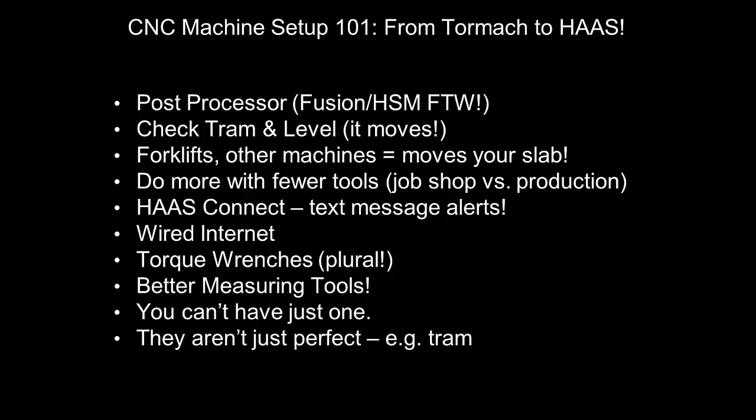Machines settle, and slabs, your concrete, settles. The level changes, the tram changes, the temperature of the room, the humidity of the room. As you run the machine, heat is created by the motors, spindle motors, axis motors, and the coolant heats up, and that changes your cast iron. And folks, this stuff is real. I'm talking thousandths of an inch. So you have to be aware of that.